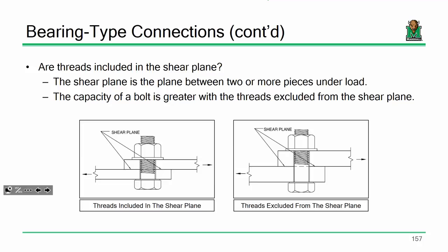So can you spec it? Yeah, but not all the time. You can't really spec it all the time. And really, in general, you just need to be able to assess both. Fortunately, it's easy to assess both. And again, going back to my original point, when in doubt, threads included or threads excluded? Included. So when in doubt, if you don't know, assume threads included. When I'm in design mode, I always assume threads are included.